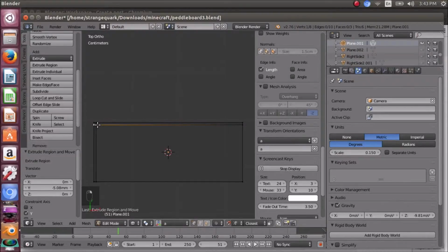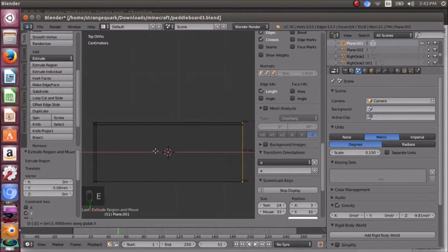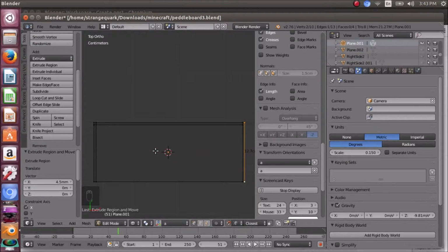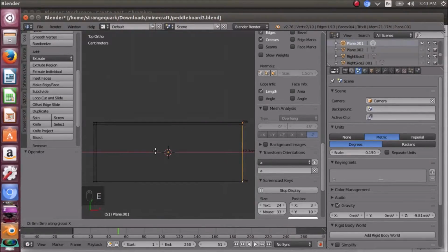And then we select these two vertices and do the same thing, EX 0.03. Whoops, I accidentally made a mistake on my extrusion, so we'll hit Control Z to back it out. Hit that again, EX and 0.038666. Hit the negative sign because we have to extrude in the opposite direction, inward. You can visually see that.